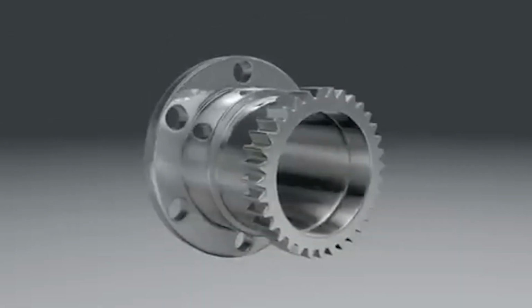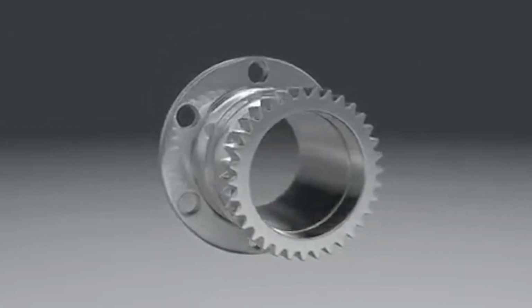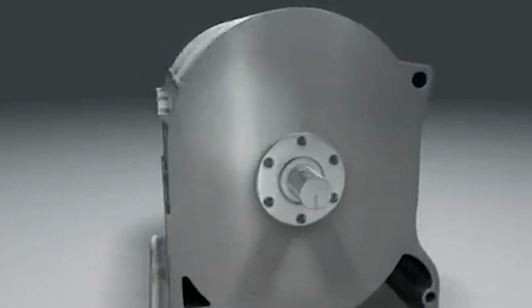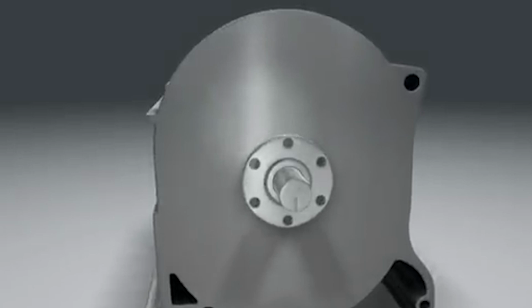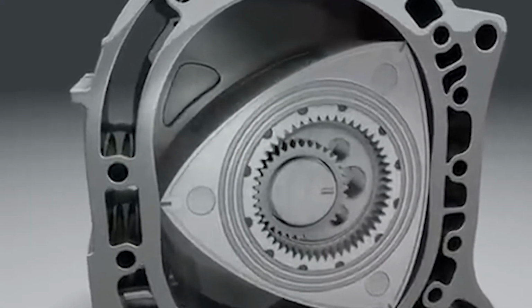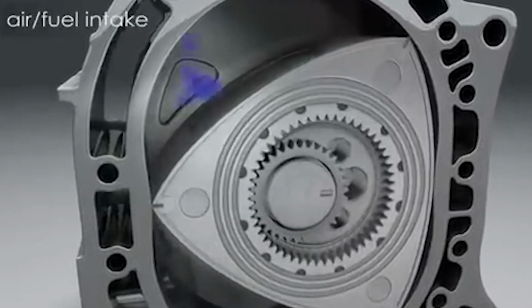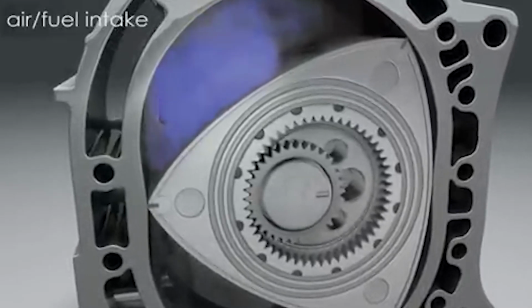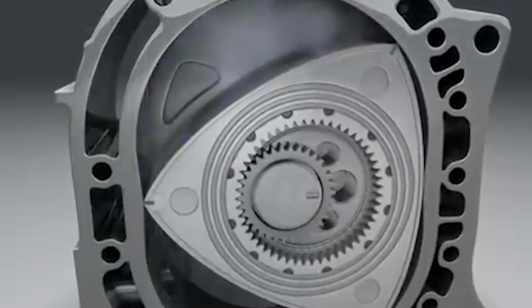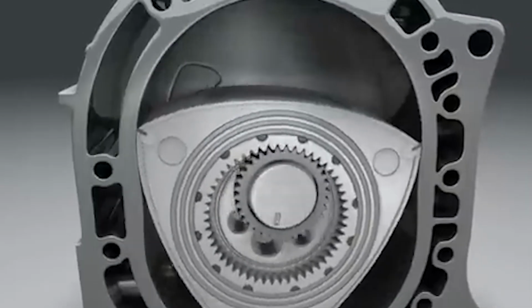So you can see as the intake fuel is coming, this piston is rotated and it is compressing the gas in between. So the inlet charge is being compressed, and here the spark plugs are there. So ignition will be caused, and this ignition will cause the expansion stroke, and hence you get the power from here. Then finally the exhaust is moving out. So this is the working of this engine.